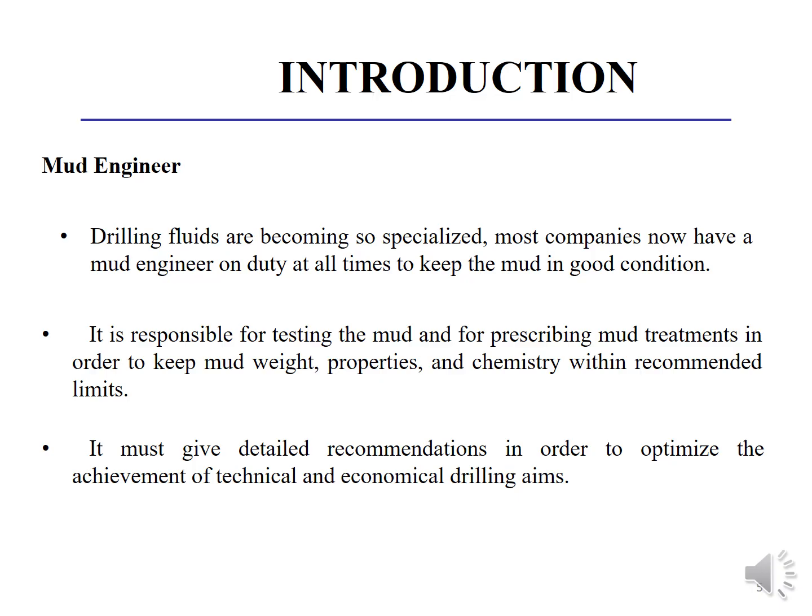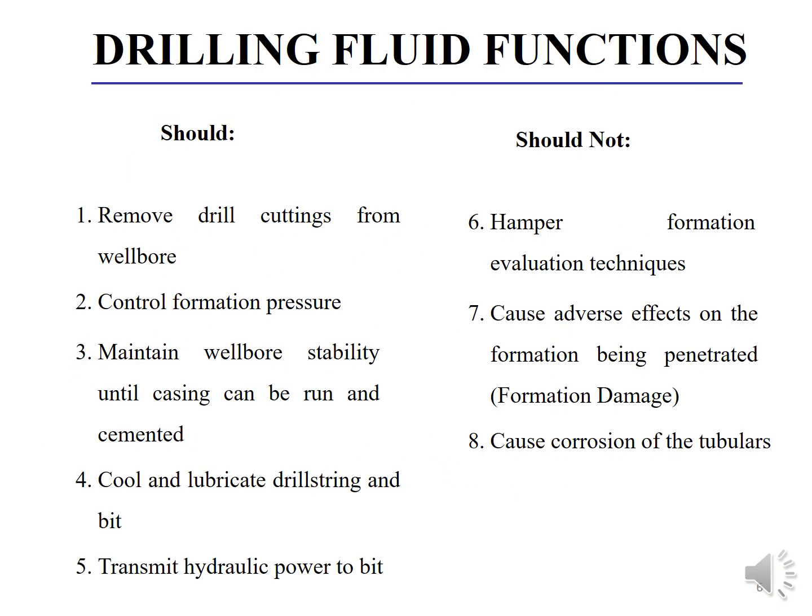It is responsible for testing the mud and for prescribing mud treatments in order to keep mud weight, properties, and chemistry within recommended limits. It must give detailed recommendations in order to optimize the achievement of technical and economical drilling aims. So the mud engineer should ensure that the selected mud should remove the drill cuttings from the wellbore, control formation pressure, maintain wellbore stability until casing can be run and cemented. So it is the last step.